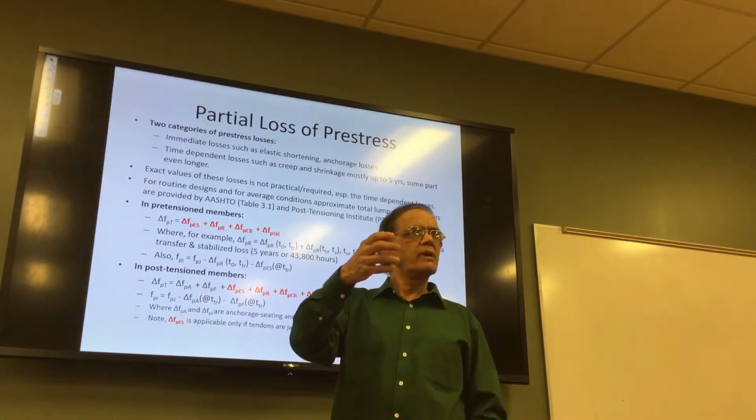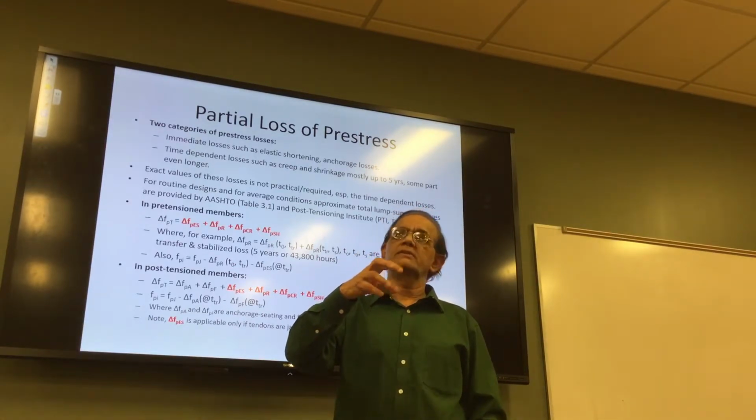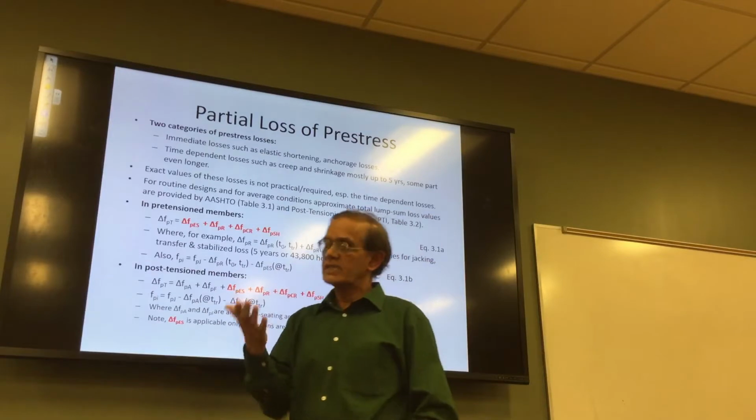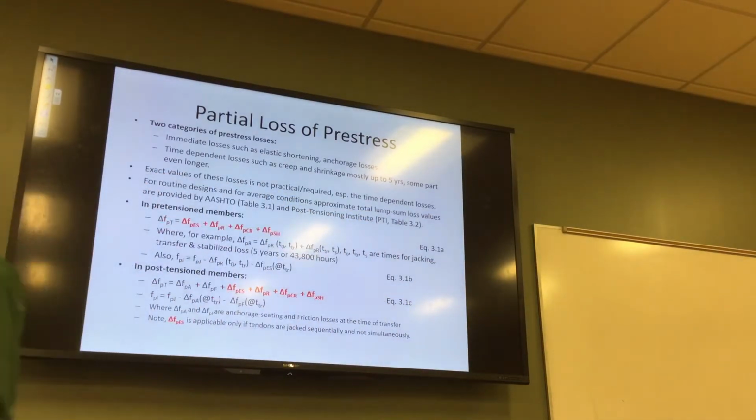Look up some websites, they'll show you even more details of this, where the material you use for wedges is harder. You know, like when you cut glass or any material, the knife has to be harder, right? Harder value, or it will not cut. If the knife is made out of aluminum and you're trying to cut steel, it won't work, right? So our wedge material has to be hardened, extra hard, so it will grip and indent on the top of the cables and the bars.